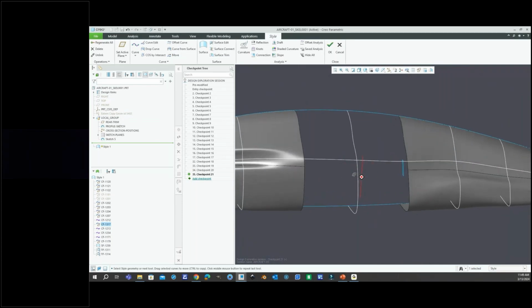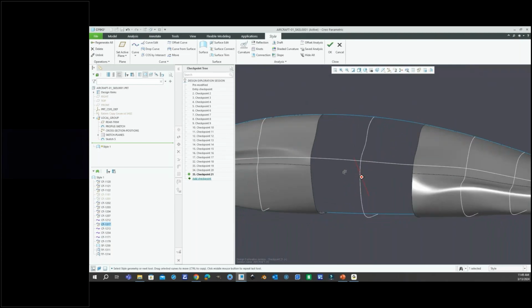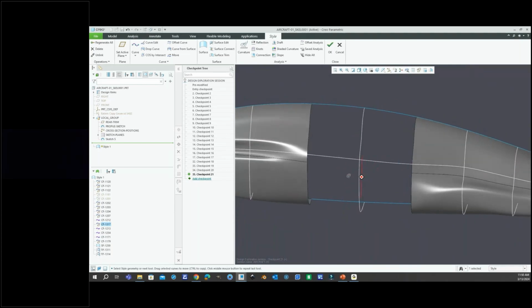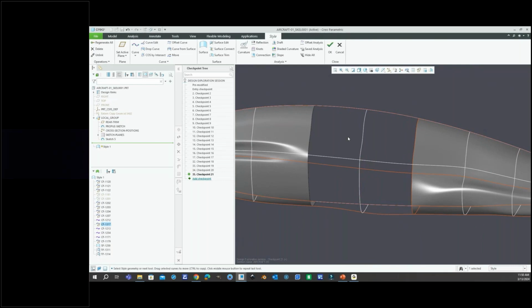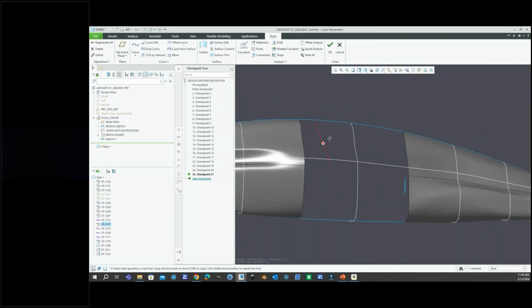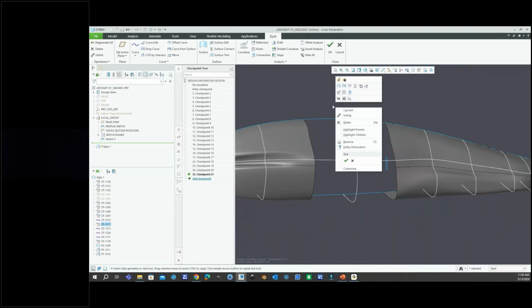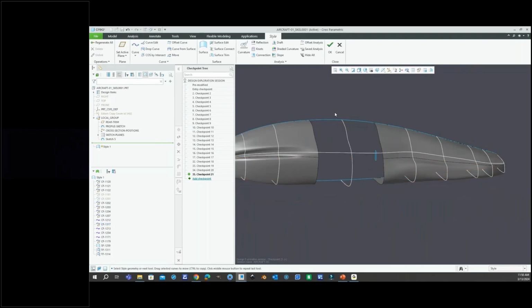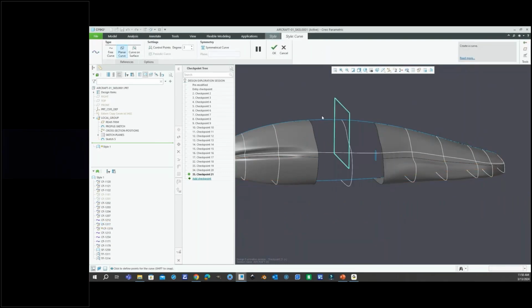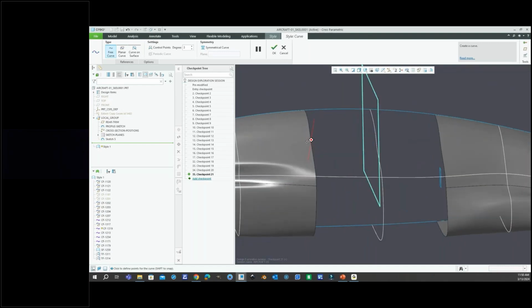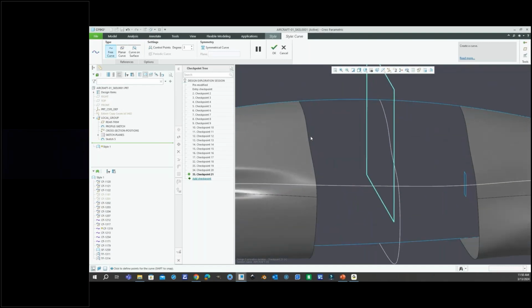I am going to create some more curves though. So to control the detail of the surface that I'm going to create, I'm going to add more geometry here. So for one, I'm going to come up here, right click, go to curve, and this time I'm going to create a free curve because I'm no longer going to sketch on that datum plane. So I'll select free curve, and to snap to the edge of the surface to the left, I'll hold Shift again,